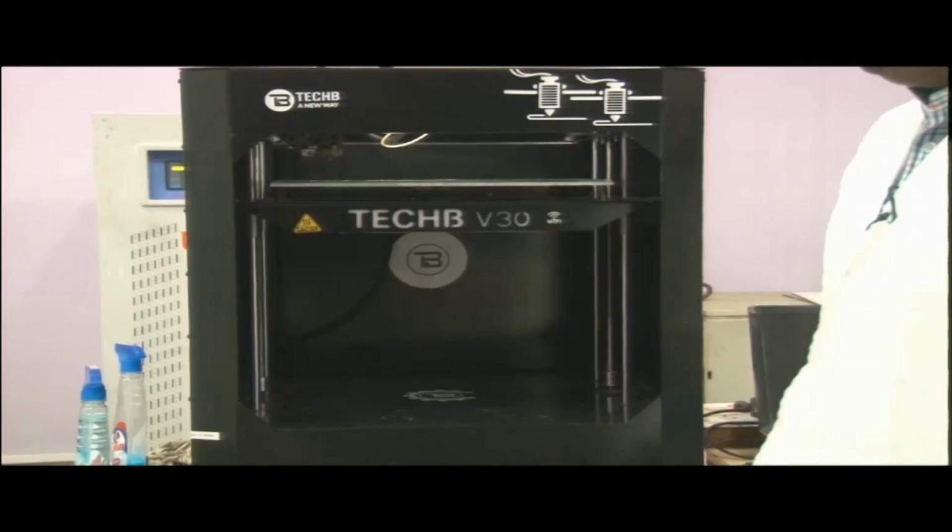The precision and smoothness of the printed models is also influenced by other factors, such as the bonding force between the layers, whether it is lower or adequate, and the weight of the upper layers that squeeze upon the lower layers. Printing defects like warping, misalignment, shrinking and shifting of layers might be there, all those things could be there.